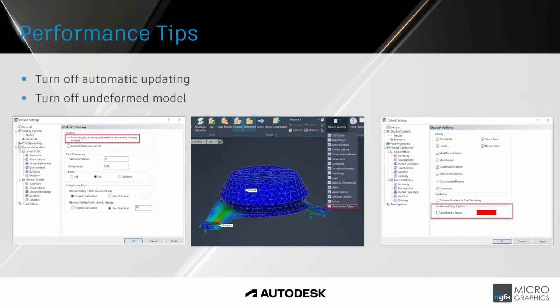Yeah. And then just for performance and being able to run this a little bit quicker, there are two options over here for displays and post-processing. You can take off automatic plot updating and also undeformed edges. Okay, so just take that off. You won't be able to see it, but it just runs a little bit better. So once again, it's about trying to run the analysis quicker, and move the model around and see it a little bit quicker.